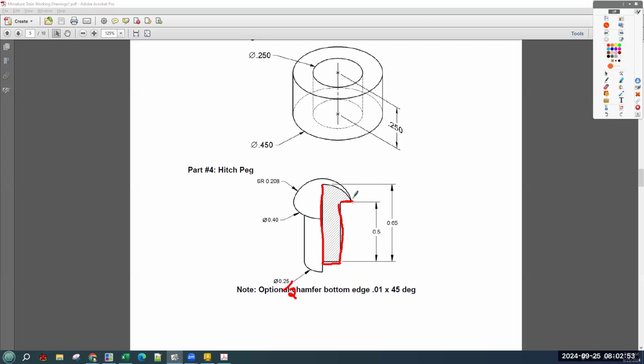This line is going to be 0.5 tall. And this line is actually, it's a little tricky because this 0.4 is the distance all the way across. So it's going to be 0.2. But either way, horizontal distances are cut in half because they are redoubled when you revolve.